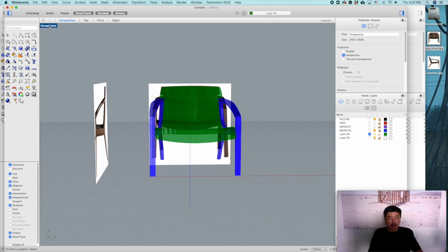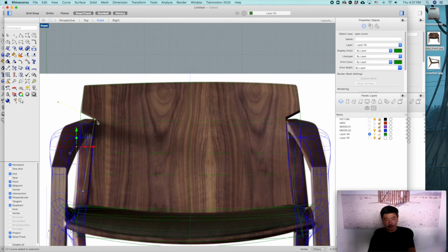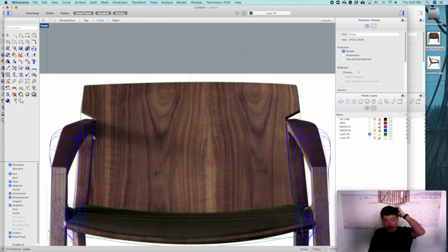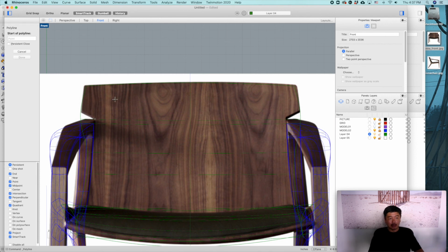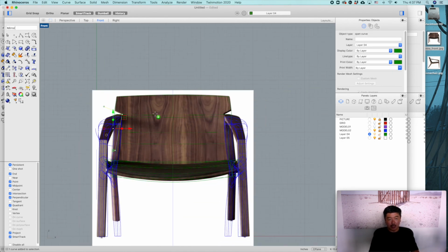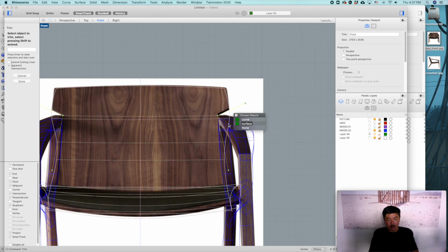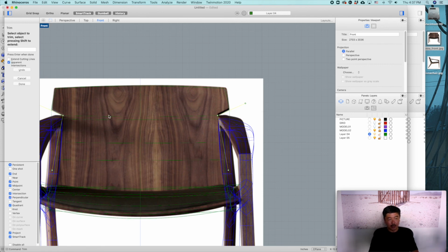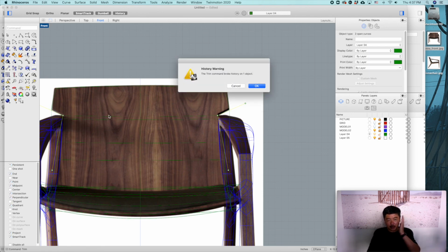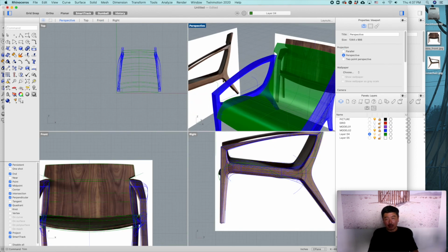So also, again, this chair has this kind of angle that is cutting out this part. So what you can do is run a polyline command and draw this kind of line, then mirror to the other side, and then use these lines to trim surface and surface, and after that you press enter. Okay, so that has created our chair for the most part.